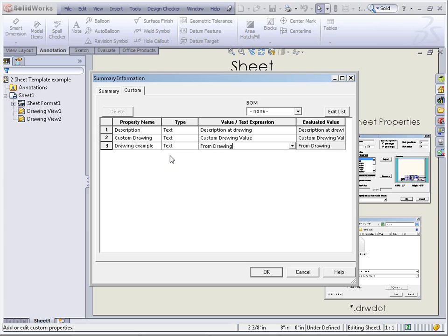Maybe half your files have half your properties. Well, you don't really want to run that through task scheduler, otherwise it'll blank out any files that have those properties already but happen to be in the folder that you were checking it on. So that could be a little dangerous. This, although slower, does work just as good.